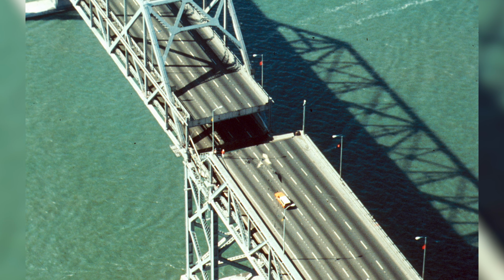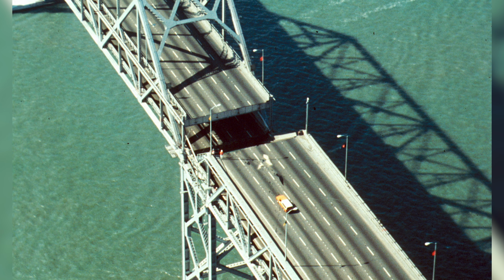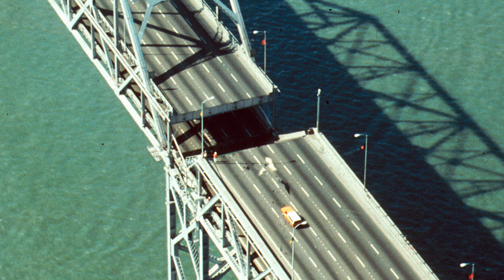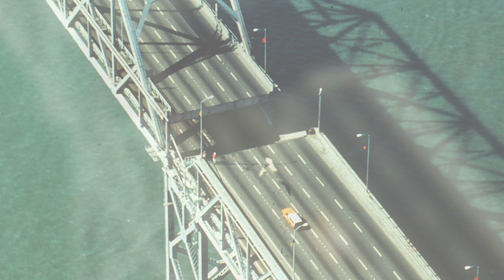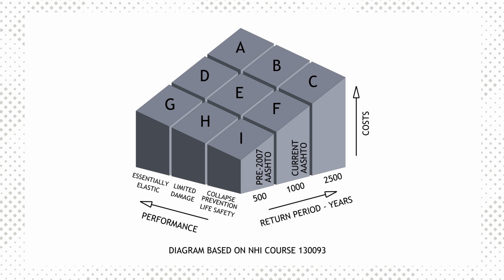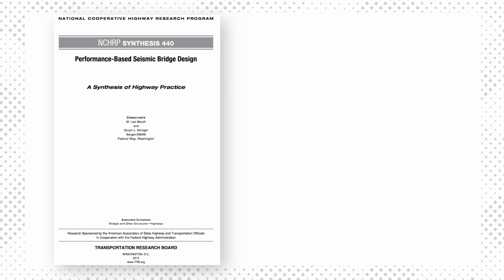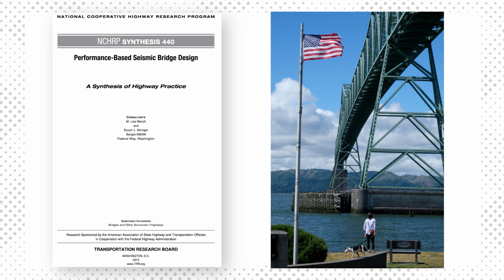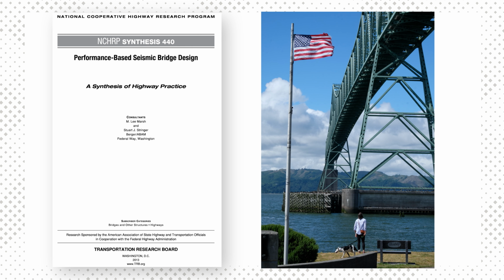Understanding that structures are not designed to resist earthquakes without damage provides insight and wisdom and requires frank conversations with owners. Plotting performance and seismic intensity against cost, we see that as we increase performance and earthquake size, structure cost increases. Current AASHTO requirements are for collapse prevention at a 1,000-year return interval. For structures that demand higher levels of performance to protect public or private interests, a performance-based seismic design method may